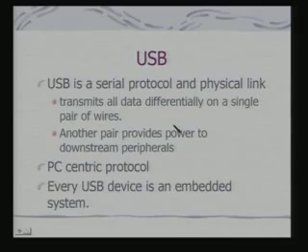In fact, USB is another serial protocol, and it also defines the physical link. It transmits all data differentially on a single pair of wires, and there is another pair which provides power to downstream peripherals. So, this bus also delivers power.